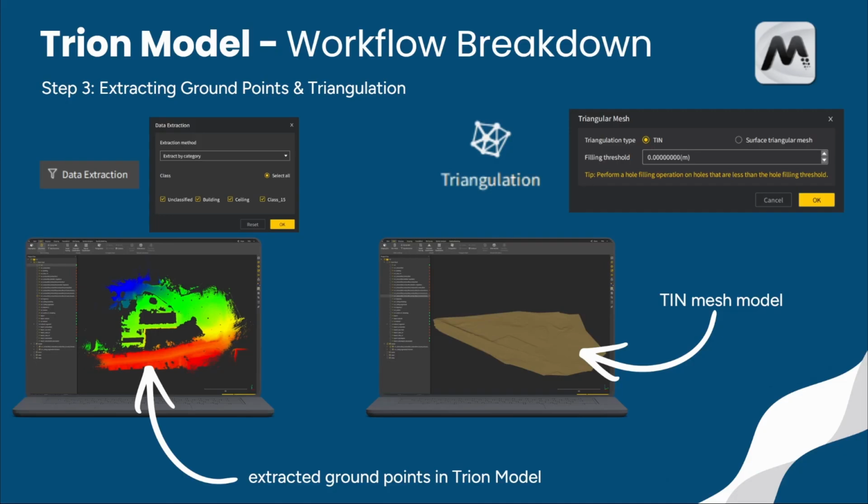And to close these gaps, we use the triangulation function based on the classified ground points. Trion model creates a mesh that generalizes and closes the missing areas. This gives us a continuous surface model, in other words, a digital terrain model, which can also be used for many other workflows as well.